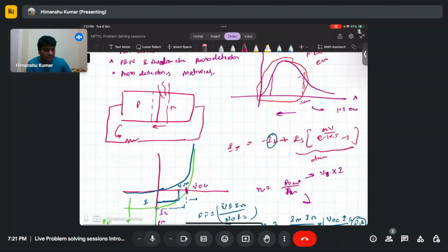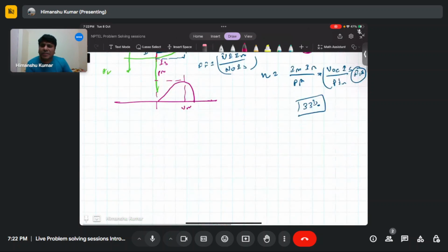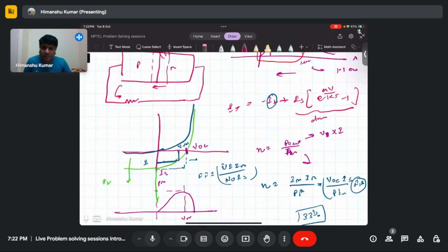The photons also do not reach the junction directly, so we create some kind of window material to make this PN junction. There are absorption losses of photons while reaching the PN junction, a significant number of losses, and some photons are just reflected due to the air and the dielectric materials of the photovoltaic cell.